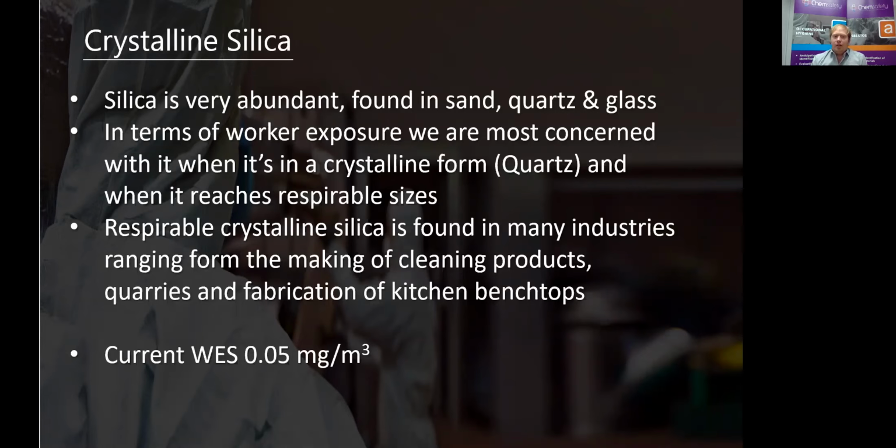So onto our case study, acute silicosis. You may have an engineered stone benchtop in your house. They're becoming increasingly popular, and you often see them in kitchens and bathrooms. They are made by mixing a finely crushed rock with a polymeric resin and then molded into slabs and heat cured. The silica content of the engineered stone is approximately 90% crystalline silica, which is much higher than the natural stone products, your marbles and granites. Workers may be exposed to respirable crystalline silica while cutting, grinding, sanding, and polishing stone bench tops during the manufacture and installation.